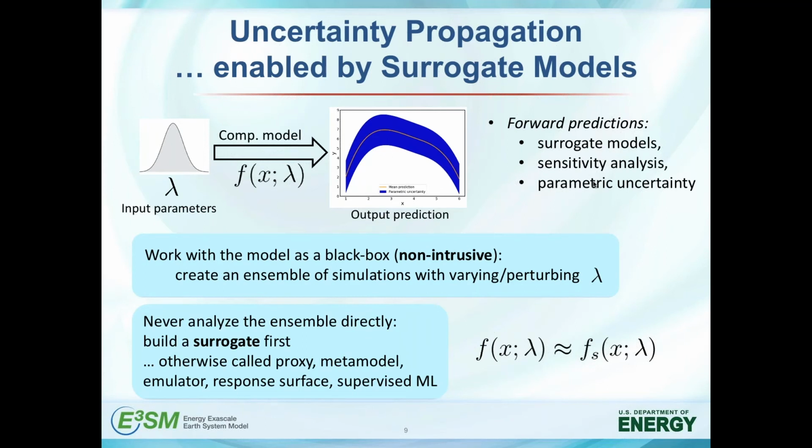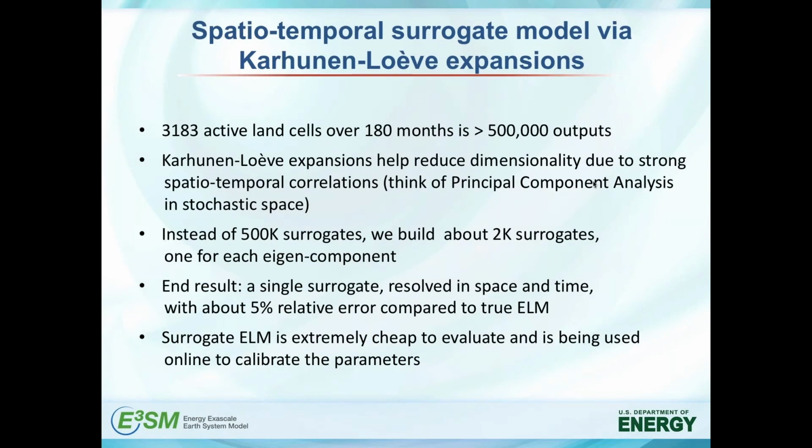It's a non-intrusive method. We don't need to edit any of the ELM code to do this. We just run some ensemble and use that to build these surrogate models. You may have heard other names for these types of models: proxy or meta model, emulator, or response surface models. So I'll talk specifically about a method that we use for looking at this global scale surrogate model.